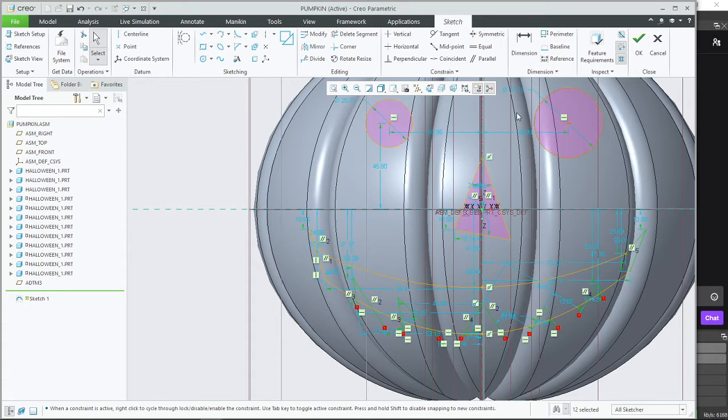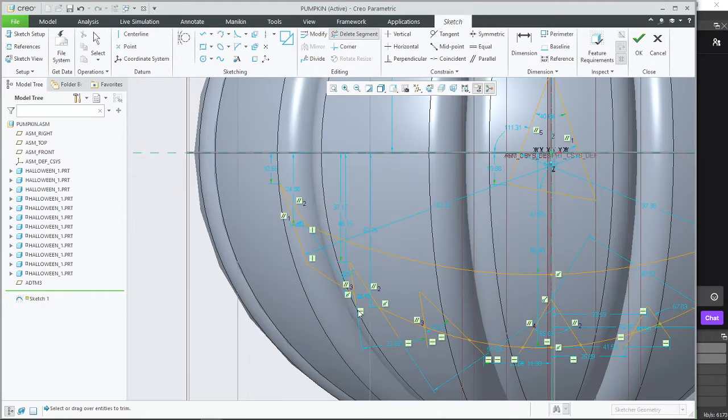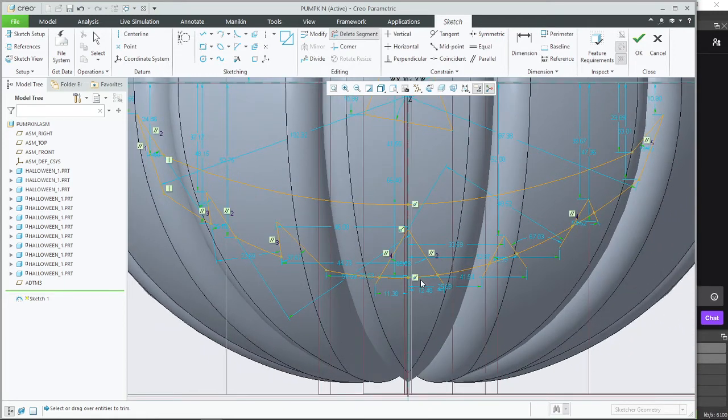Now, you see these are purple, that means this is done, but this isn't. If you want to do anything with a sketch, the sketch needs to be a fully closed surface. Purple indicates that the surface is closed. If you don't see purple, that means there's an error somewhere, and we have errors here because I free drew lines over lines just to indicate roughly where something would be. And now I have to delete all the excess segments.